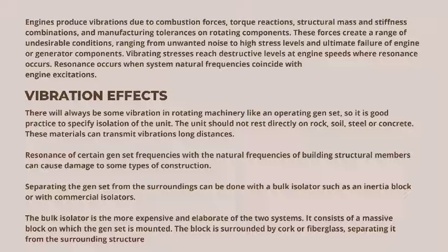Engines produce vibration due to combustion forces, torque reaction, structural mass and stiffness combination, and manufacturing tolerance on rotating components. These forces create a range of undesirable conditions, ranging from unwanted noise to high stress levels and ultimate failure of engine or generator components. Vibrating stresses reach destructive levels at engine speeds when resonance occurs. Resonance occurs when the system's natural frequencies coincide with engine excitations.